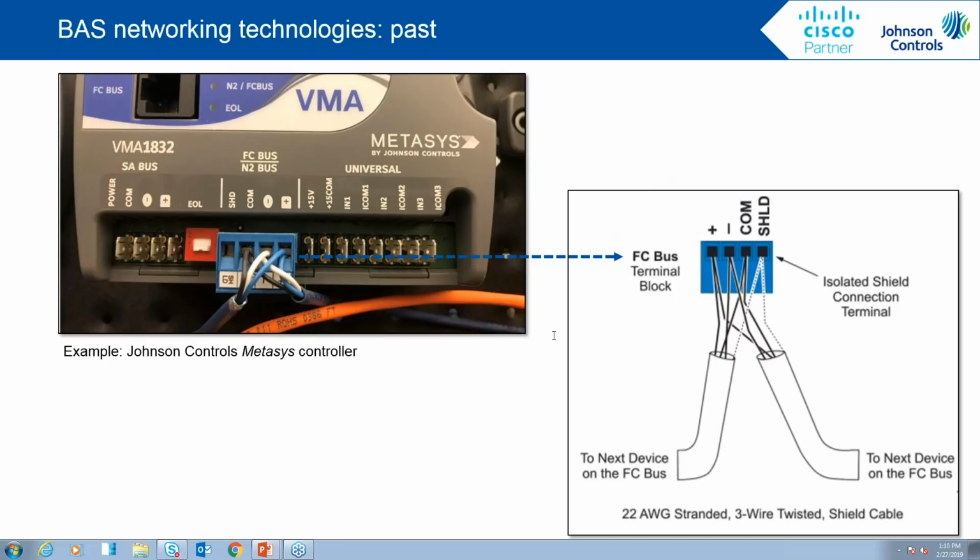I've heard of instances where people are actually dragging oscilloscopes out to job sites to troubleshoot those kinds of networks. We ourselves have developed proprietary field bus inspection tools to troubleshoot these kinds of issues. I know that there are other products on the market, but they're kind of disparate and there's no industry standard there.